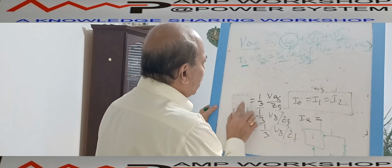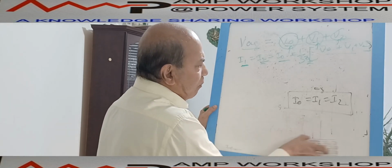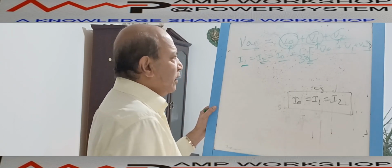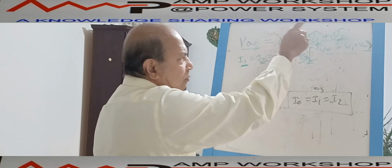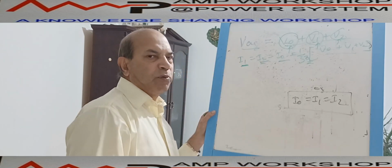So how can that condition be met? You see, a very important observation here. There are two relations over here. One relation is zero sequence current, positive sequence current, and negative sequence current are equal. That is one relation. Another relation, positive sequence voltage, negative sequence voltage, and zero sequence voltage, if we sum them all up, then we are getting the phase voltage of A.